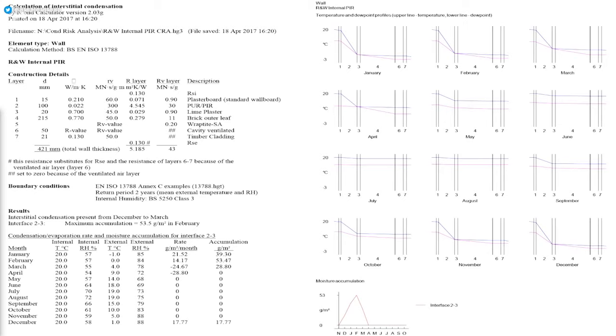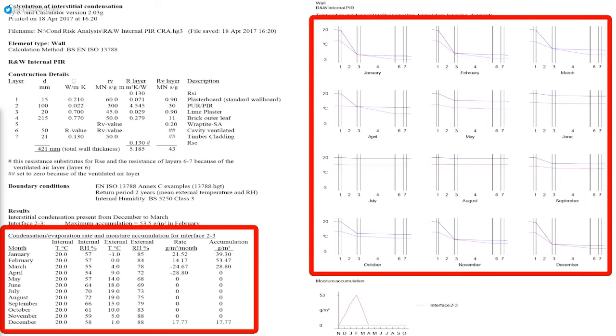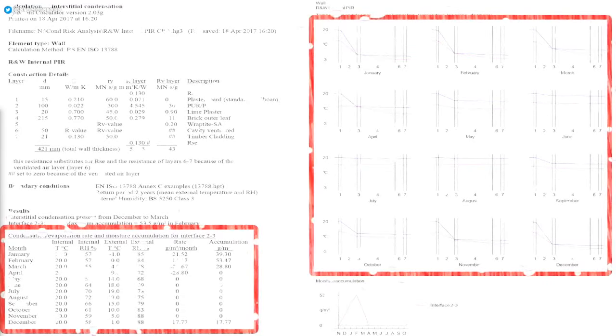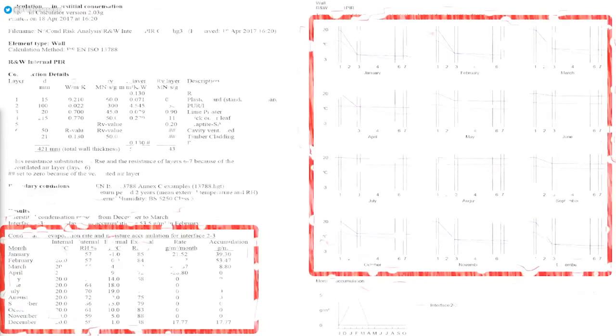Developed back in 1958 for use in lightweight buildings, the simplified calculation used by the Glaser method is based on average monthly temperatures, vapour pressure, and steady-state conduction of heat to determine if critical condensation points are reached within 1 year. The limitation of this approach is that Glaser assumes vapour moves only one way, from inside to outside. It also completely omits the key feature of driving rain from its calculations, does not measure absorption or porosity, and therefore fails to identify potential risk attributed to the aspect of moisture storage.